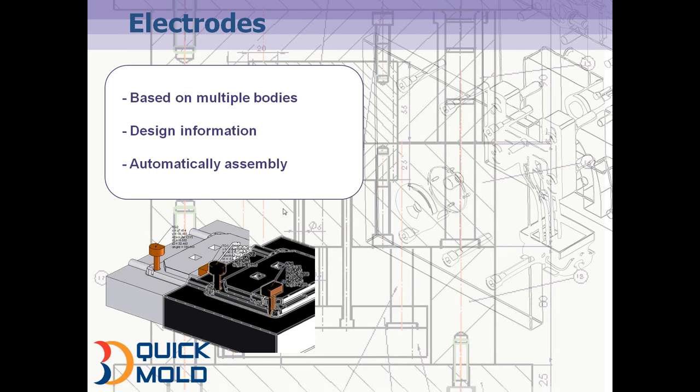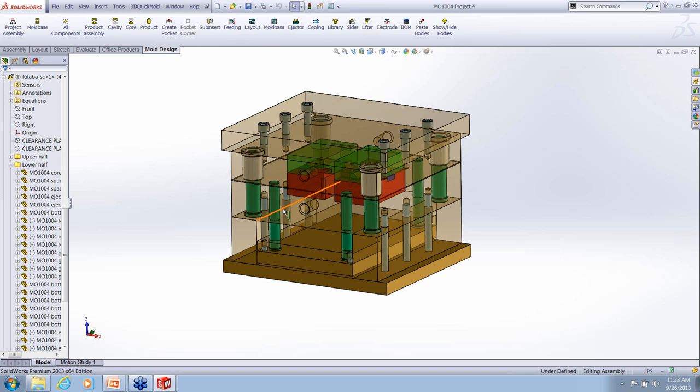The moment you define holders, immediately it will give you the distance. Suppose you define a reference point in the core or cavity, any area, then from that particular reference point it gives the difference from the x and y origin, and also the spark depth, or total depth for sparking these particular complex shapes. I'll brief you on these things with the live demonstration.